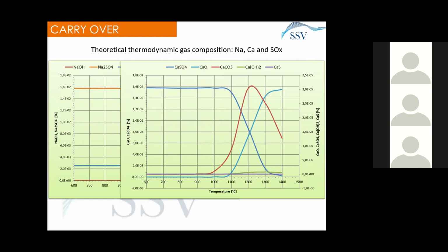Well, just if there was a correlation between the waste gas emissions and the amount of sulfur. Yeah, sure, for sure. There is a correlation. The parameters correlated in this case are the temperature, where you are going to see if there is a condensation of some material, for example, sulfur compounds, and the concentration of the sulfur compounds in the gas. So yes, the emission is correlated to condensation of sulfur compounds in the regenerators.